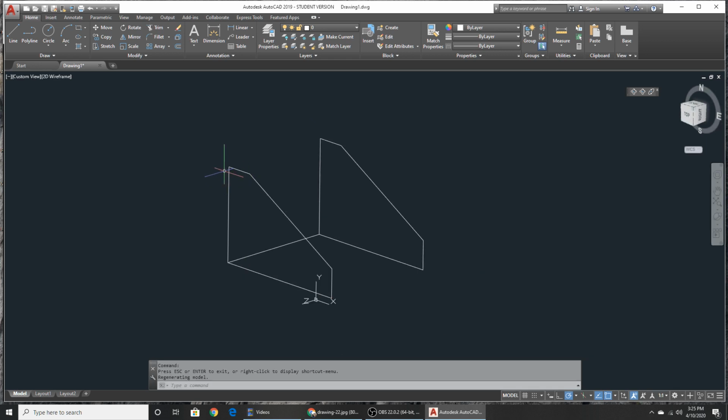Now I didn't dimension any of this stuff yet, so I could have made a mistake somewhere, and now that I've copied it, I could have copied that mistake, and that could present a problem later on. But this is for demonstration purposes only, so I don't plan on putting any dimensions on it. We're just going to go through the process. I'm going to now copy this line, grab that endpoint, and this line, it represents an edge that goes from one of these surfaces to the other. So that's all we need to do, set that all up just like that.